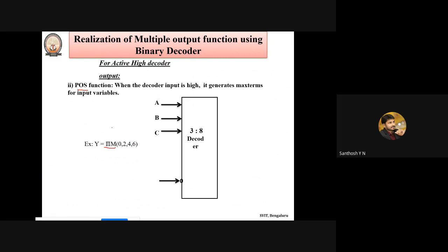Again, this function can be implemented by making use of a 3:8 decoder only because the length stops at 6. If it had 12 or 14, after 6, then you would be supposed to use a 4:16 decoder. Since we have considered an active low enable signal, you have to provide 0 in order to activate this 3:8 decoder. Now there are 8 outputs, that is Y0, Y1 till Y7. I am taking the output Y0, next Y2, next Y4, next Y6.